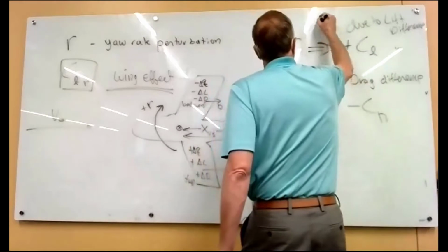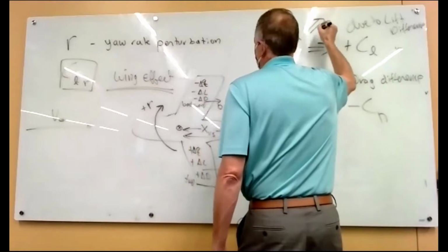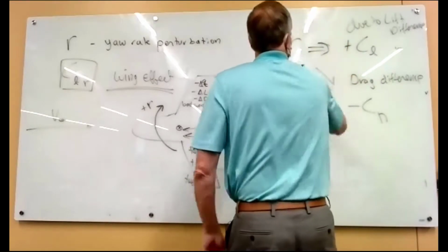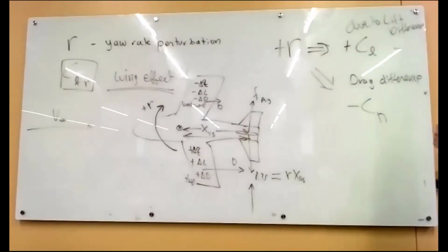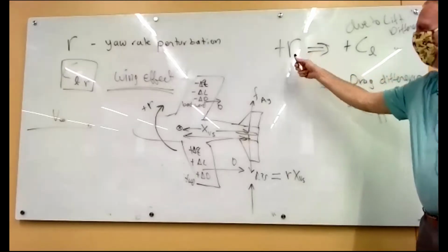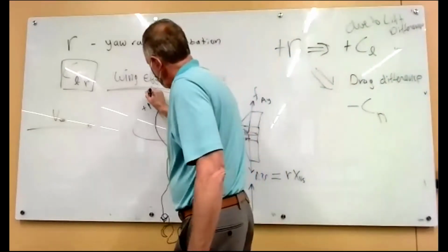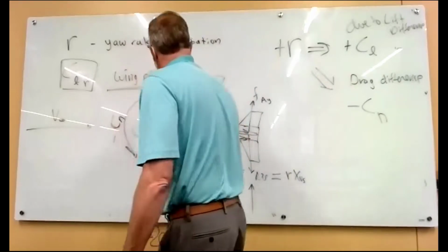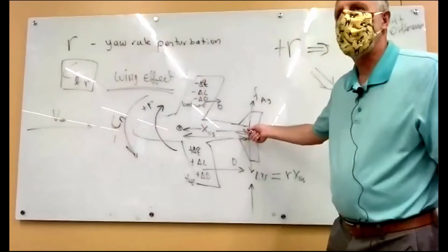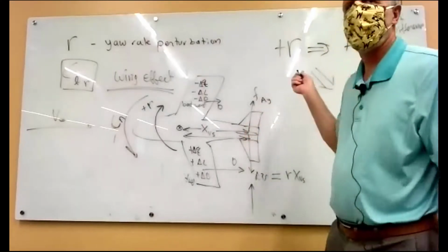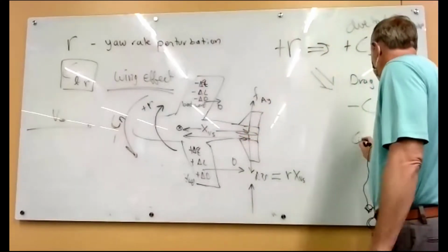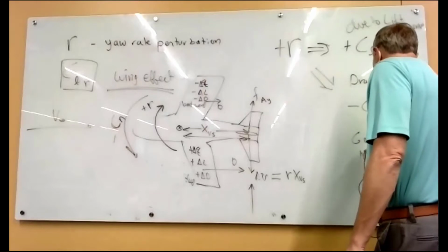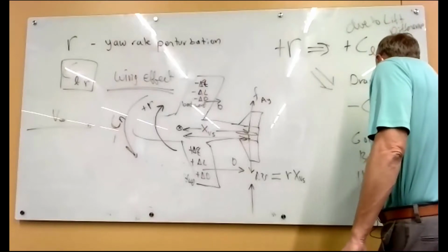And we might as well write the side force up here. Oh, that's the vertical tail effect, never mind. So we get this happening. We've had a yaw, airplane's yawing this way, and we're going to get a negative yaw as a result. We got that from the vertical tail, and we get it from the wing. So is this good, bad, or just ugly?